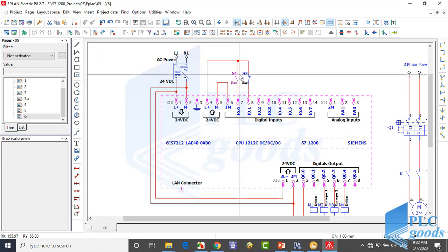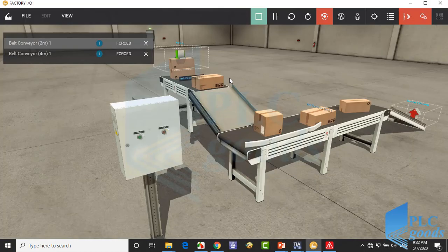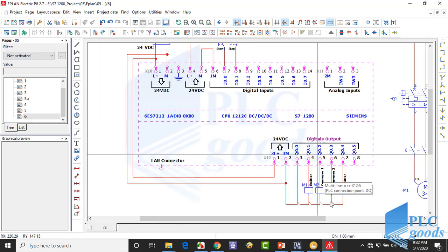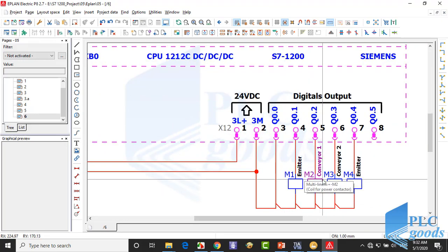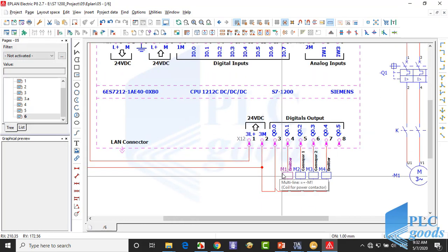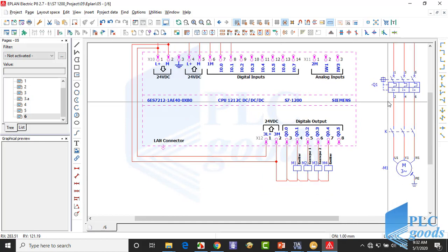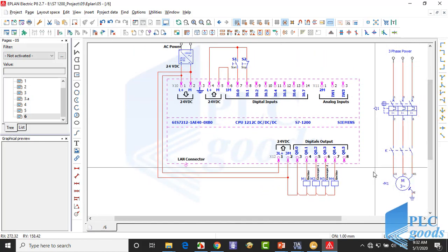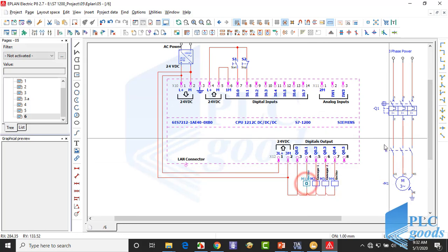This can be our PLC wiring for this project. There are two start and stop push buttons, and we have four outputs which are connected to the PLC. As you know, for devices such as conveyors, which a PLC can't turn on directly, it needs relays and power circuits too. But here, we only want to learn to use and program a PLC. So to test our programs, we don't need this part.